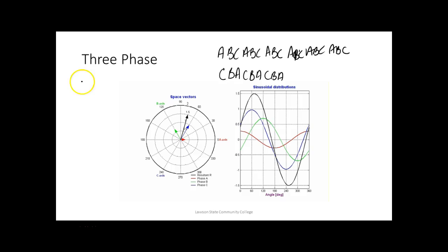Of course, we don't see it from that point of view. We see it L1, L2, and L3. So the normal way to reverse a three-phase motor is to reverse these two right here, L1, L3. That's the industry standard. And what we want to do is do things according to the industry standard, so the next person that comes in there doesn't have to figure out what we did, right? You understand? And get themselves hurt. So this is the industry standard to reverse L1 and L3. L1, it works better with ABC, but it would come up and do exactly the same thing.